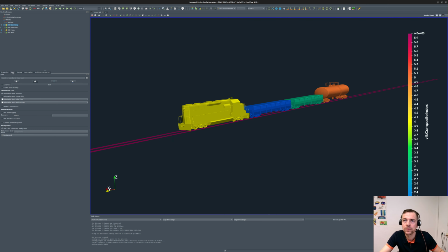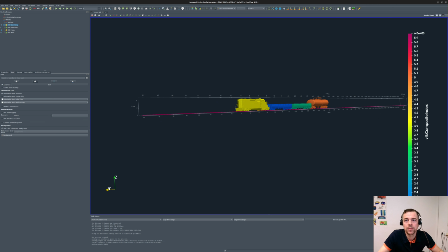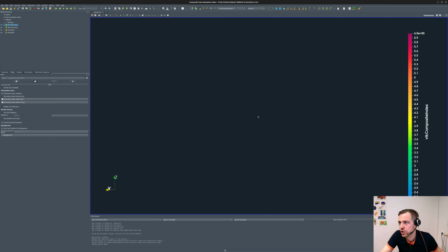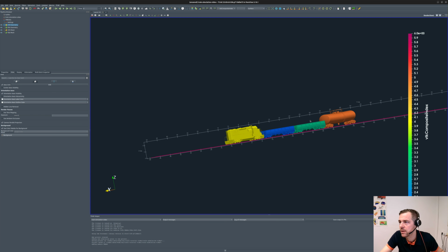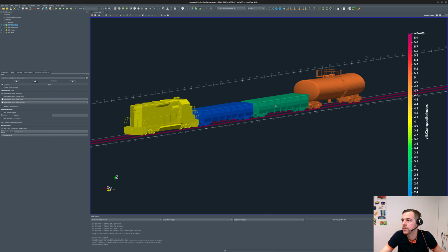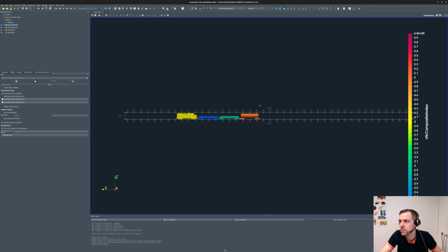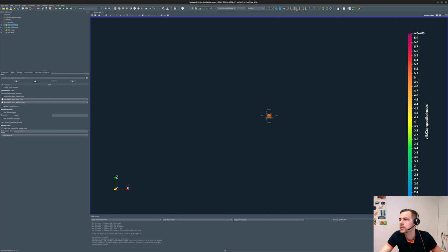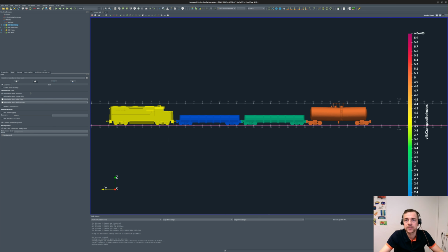Before I do that, I like to visualize a couple of things. I like to see the grid, to see the dimensions, and I usually prefer having the camera parallel projection in ParaView, which helps me to see things without perspective, because perspective for engineers sometimes is not doing a good service. So I'll set the camera parallel, so every point is perpendicular to the screen, as you know. It allows me to show my model with the ruler in perfect orthogonal projection. Okay, so I'm fine with this.